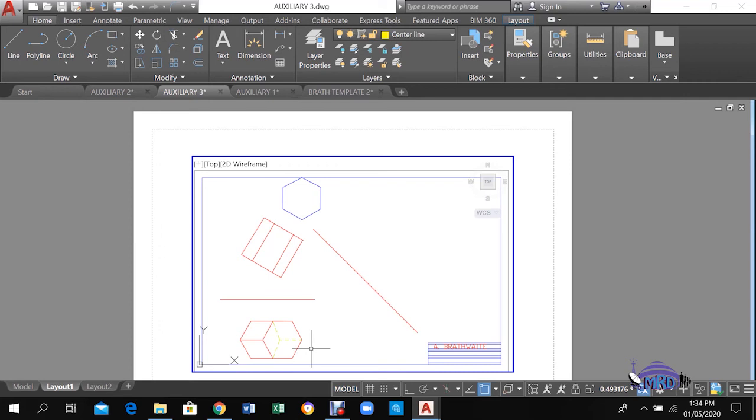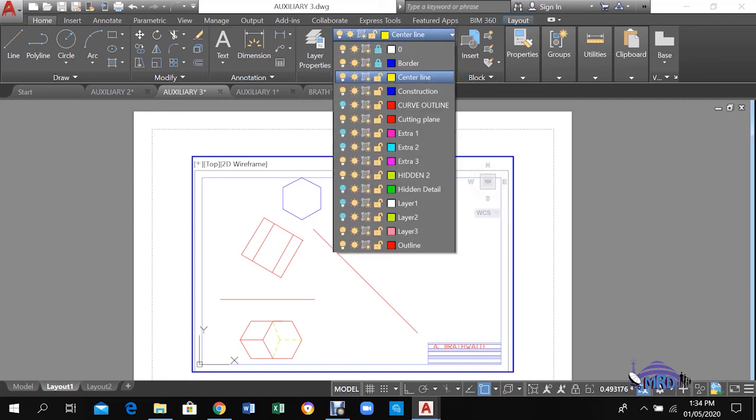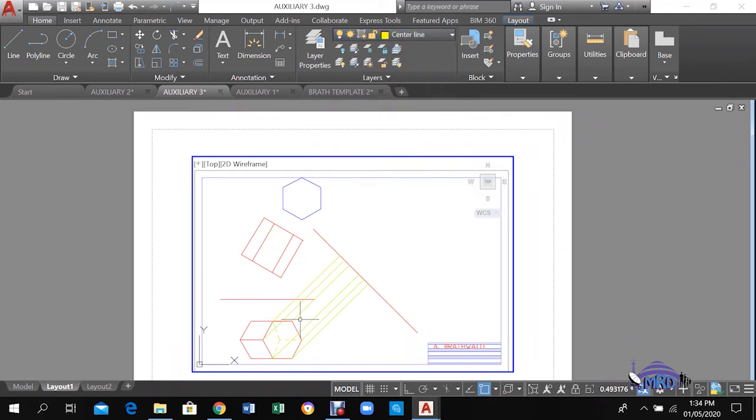Now, as we said before, there are two hexagons. There's a hexagon at the top, there's a hexagon at the bottom. So our process will go something like this. We have our 45-degree angle in already for the XY line. So the first thing that we will do then is pull in the projection lines for our first hexagon. So this is our first hexagon here. These are the projection lines going up to XY.